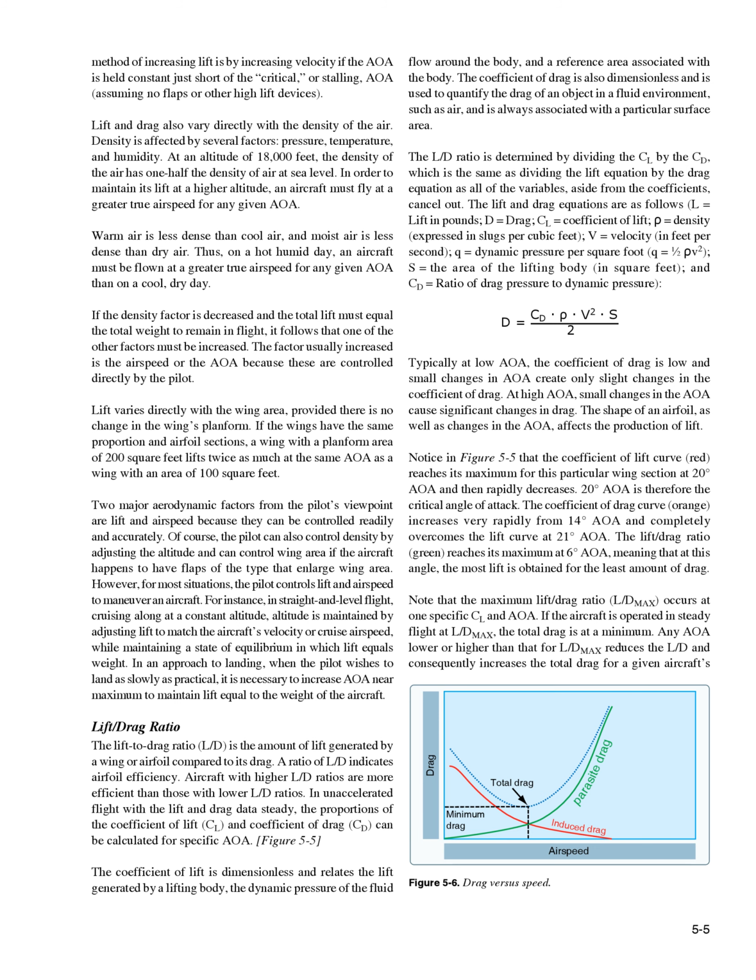Notice in Figure 5.5 that the coefficient of lift curve, red, reaches its maximum for this particular wing section at 20 degrees AOA and then rapidly decreases. 20 degrees AOA is therefore the critical angle of attack. The coefficient of drag curve, orange, increases very rapidly from 14 degrees AOA and completely overcomes the lift curve at 21 degrees AOA. The lift/drag ratio, green, reaches its maximum at 6 degrees AOA, meaning that at this angle, the most lift is obtained for the least amount of drag.